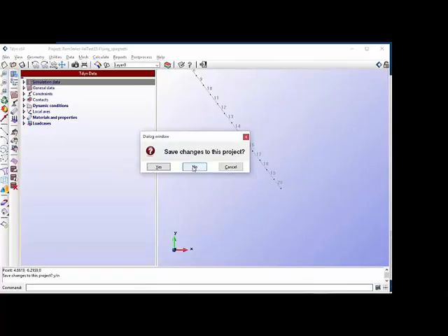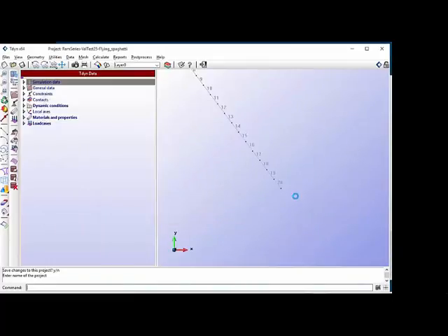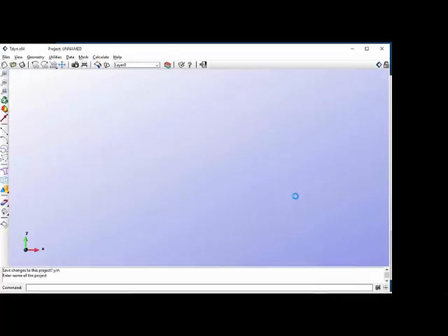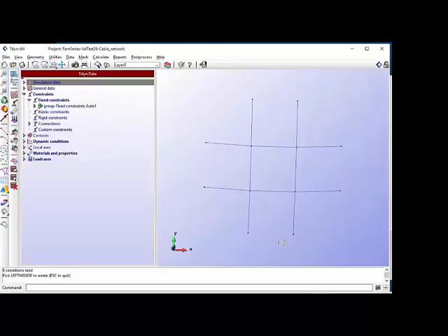Of course, this model, we have also used it for validation, so you can find it in our web page in the corresponding section. So while it gets loaded, I will just explain a little bit this model. It's just an example consisting of a plain cable net, which is subjected to both static and dynamic loads. And of course, the dynamic load in this case corresponds to an earthquake loading, which is applied in the vertical direction of the structure.